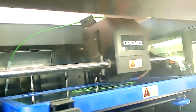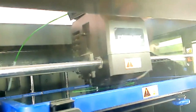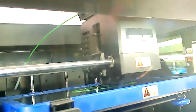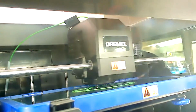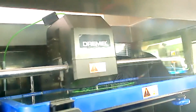And then you can see, I believe on the video, as it puts down this first layer of material. And so the machine will go through and start to put down the first layer of polylactic acid, PLA. And then after it does the first layer, the bed will move down 0.3 millimeters and start extruding the next. Okay, now if we take a look at some of the material from the textbook,